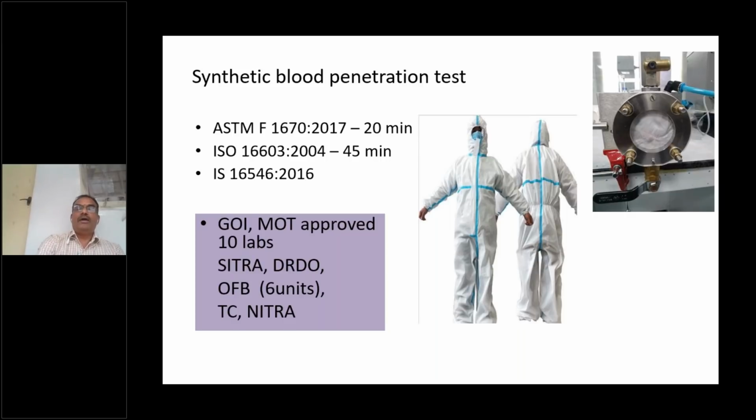So in fabric, they'll take a portion, like the chest portion or the thigh portion, they cut the fabric and test it. So normally 70 GSM and above coated fabrics pass in the fabric stage. That you can keep in mind if there are any manufacturers in the group who are just watching it. So anything above 70 GSM is preferable with a coating particularly. And in this seam seal taping, be careful with the high temperature during the taping. It should not be reduced below 300 degrees centigrade, and ensure a good pressure on the roller where you get a good seam seal, where you get a pass.